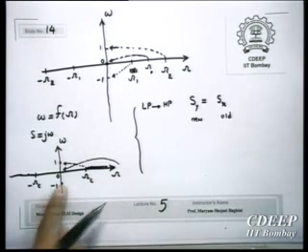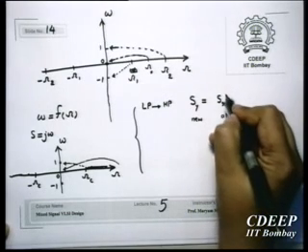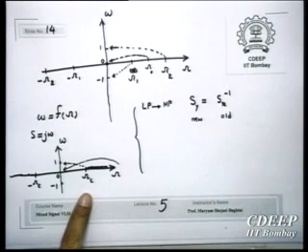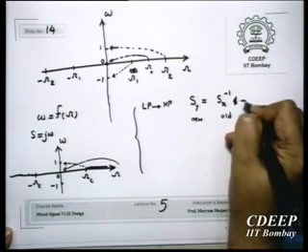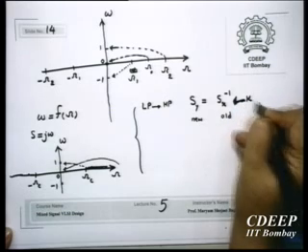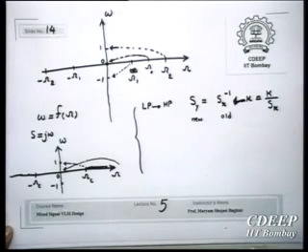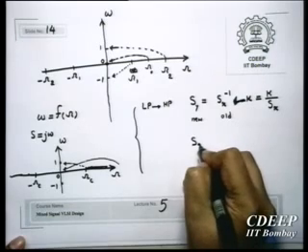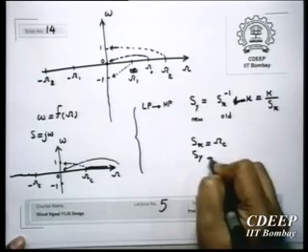I want to make infinity to be 0 and 0 to be infinity. Therefore, this says that I should reverse it, so this should be Sx inverse. I need just a normalization factor, a coefficient k. So it will be k upon Sx. What is that coefficient? I want that when Sx is equal to omega c, Sy should be equal to 1.